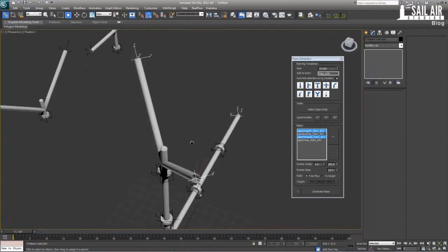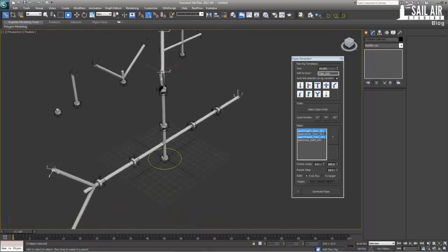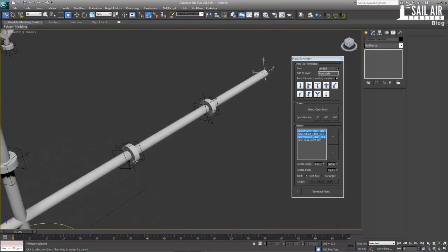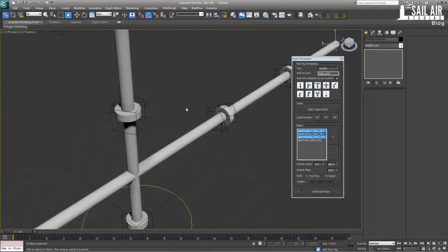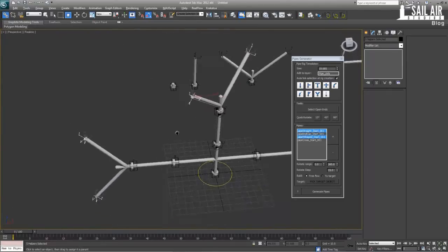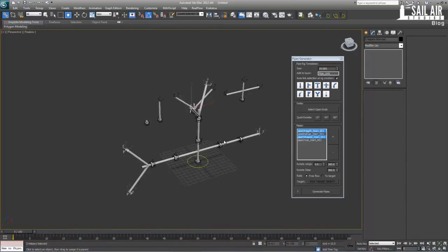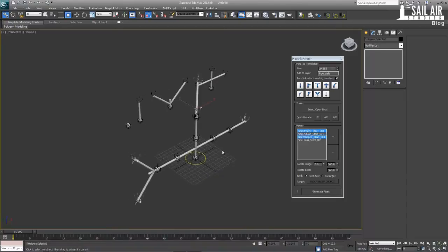As you can see, it is offsetting itself, and the rotation range is between 0 and 360 with a step of 15. So every iteration, you can see the rotation is going by 15 degrees on, I think, the Z. Yeah, it's on Z. Around the Z axis. If you don't want that, you can set it to 1. I think you can set it to 360, which is 0. If it actually flips all the way around, it stays similar to 0.